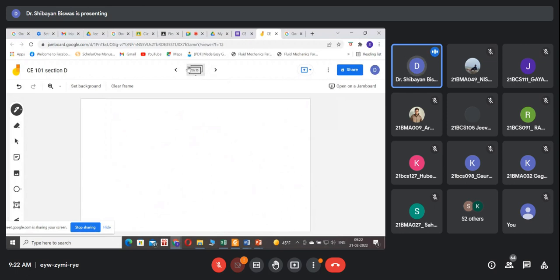So now again, if we go back to this part, till now we know that sigma is equal to E by R into Y. F on a layer, F means force, is E by R into Y into dA, because we are considering this case where this is the elemental area and this is the y. So E by R into y into dA.